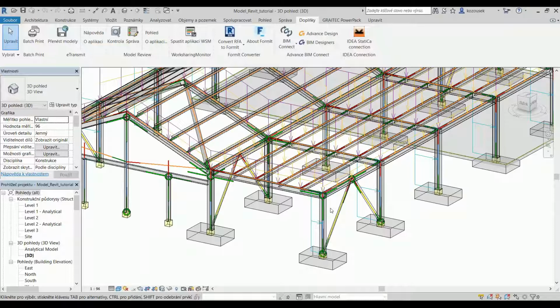This we type in, and it asks us to select the node of the joint and select members of the joint, which we have four here. This is a truss roof joint, and we select the items like plates, bolts, and welds. Now this joint is being exported to Idea Statica, which opens immediately. And here we can see the joint imported.